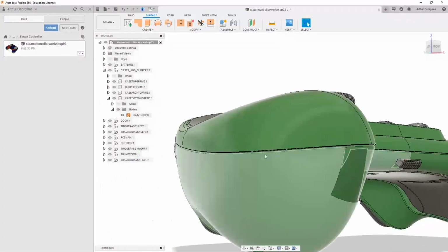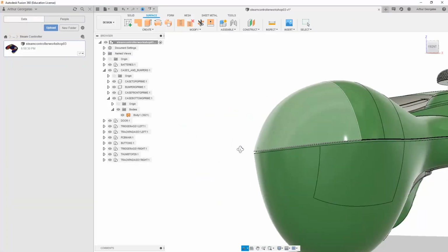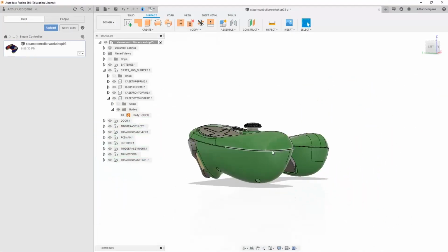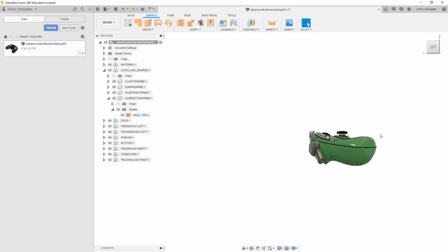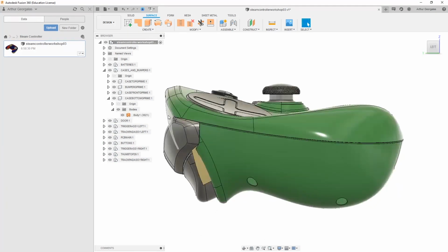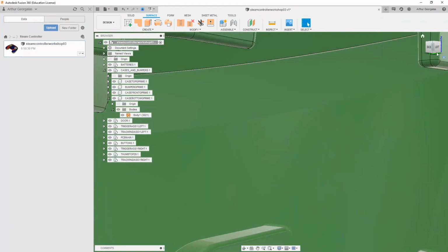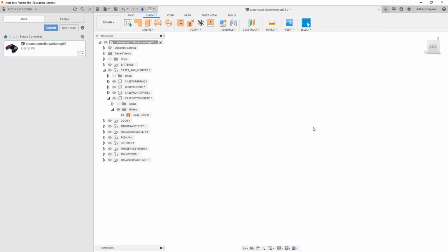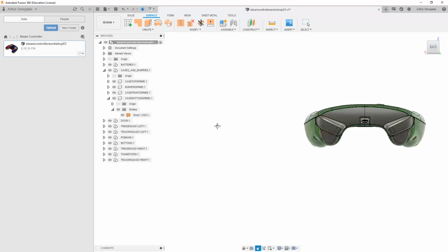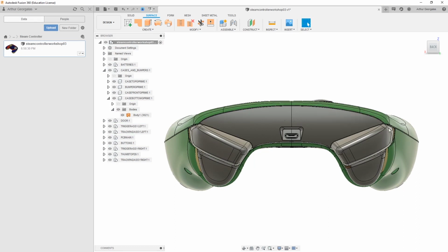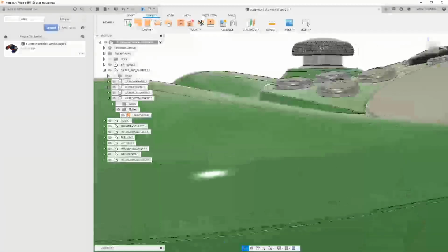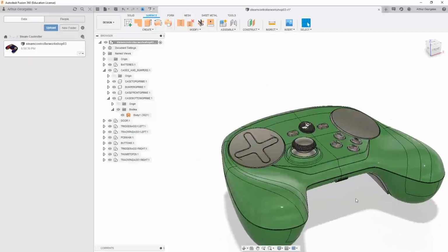We want to observe how the part line works. That's a really important part of this project, looking at the part line. If we have a look from the side, it looks like just a regular sweep through shape here. But once we move to the back, we can see that it then comes up across here. So we can't just split it simply. We have to use a 3D shape to do that, and we'll probably get into that in the next video. So what can we do? What can we learn from this?